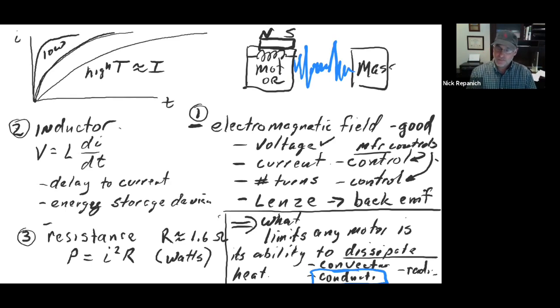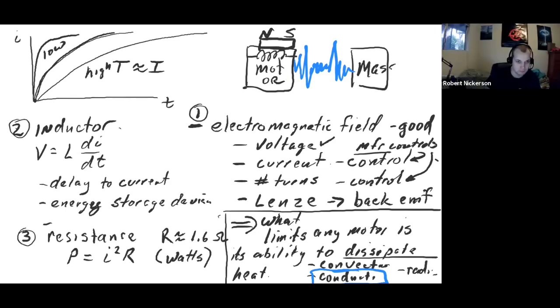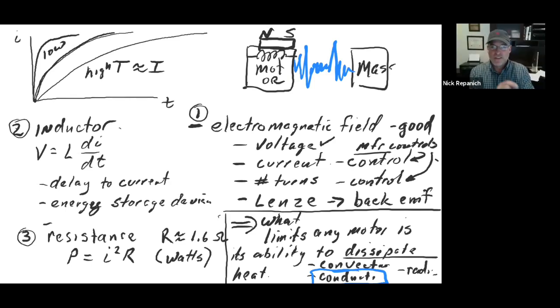And just back to the tolerances and conditions, when you see a motor with torque, what's one of the conditions that they might assume that you're doing when they tell you you can get a certain amount of torque out of a motor? Properly cooling it. Heat sinking, right? Yep. If you look down, it's one of those asterisk things like, okay, this is asterisk, assuming you have a heat sink with 80% contact and it's pulling heat out the front versus, they would say, free air or something like that.